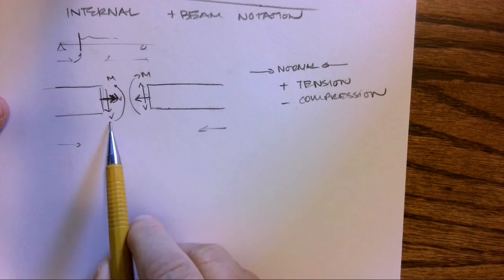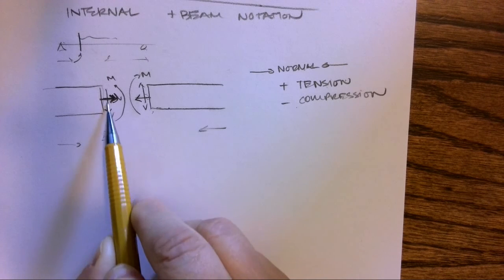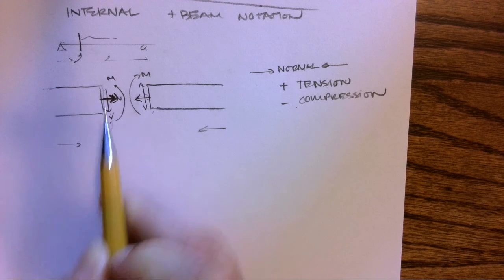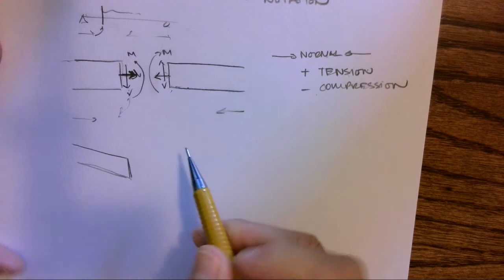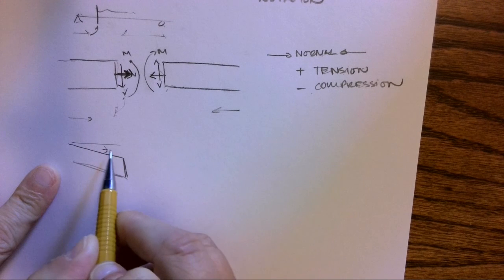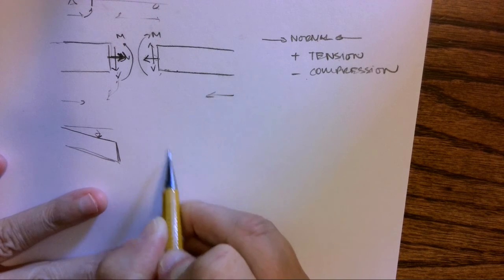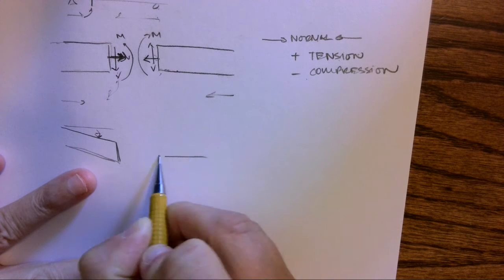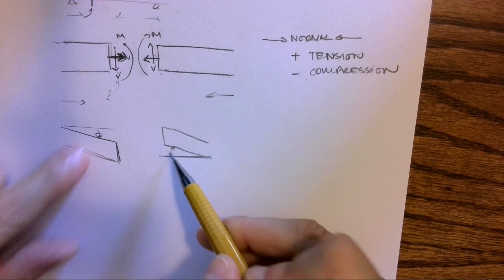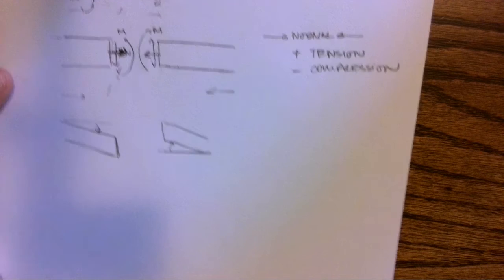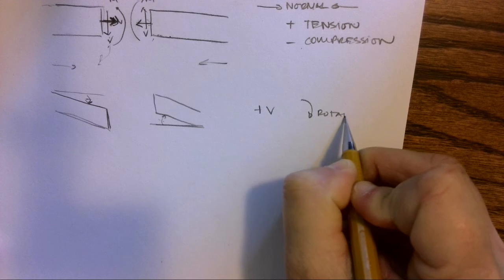When I look at internal shear, positive shear gives me clockwise rotation. So if I push this down, then we are rigid body, and we can see that it's rotating down, and we would have an angle that we can calculate, which we'll be doing in strengths. Again, if I have this member, those are both clockwise rotations. So that's what the positive shear is going to give us. Positive shear gives clockwise rotation, which is opposite of right-hand rule.